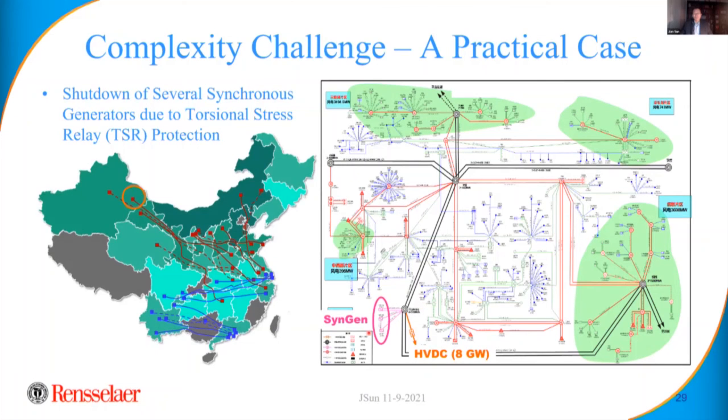Next, not far away from the HVDC station, is this coal-fired power plant, about 4 to 5 gigawatts. And the purpose of those is to stabilize the local AC network for that classical HVDC. Those who studied converters or classical HVDC know that you need a decent AC grid to operate a classical HVDC, and that's part of the reason for having those synchronous generators. The rest of the system is all wind and PV.